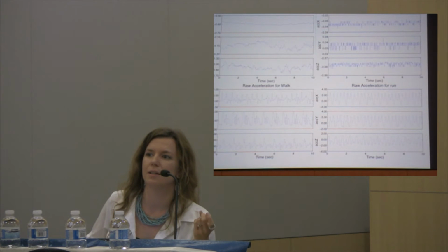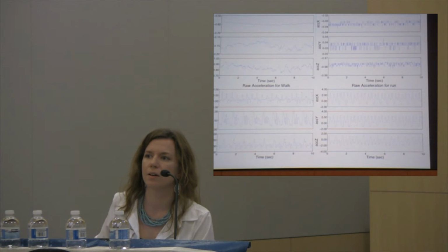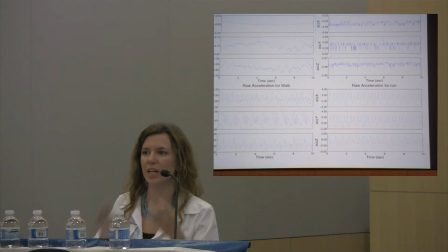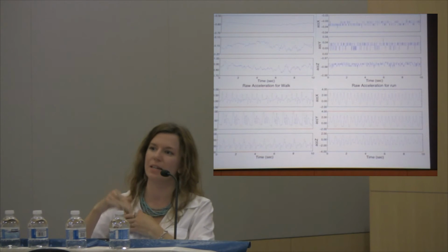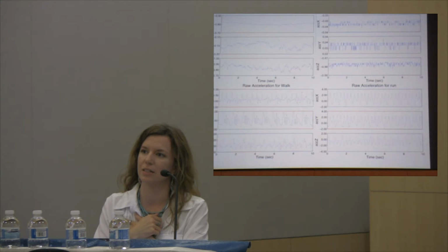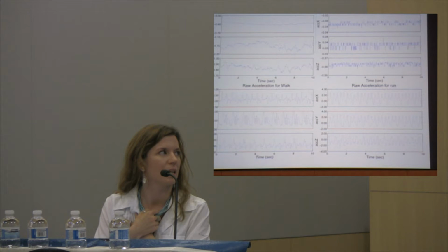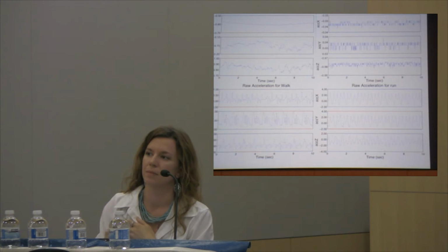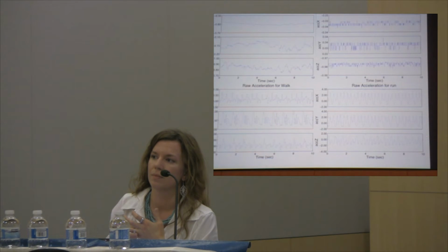Yes? What was the cause of the noise floor in the cell phones? Is it a mechanical noise, electrical noise, sensor? If you just isolated the accelerometer, could you get a better smartphone-based sensor? I don't know. We only tested the noise floor in the chassis of the phone itself. We haven't really explored that. You can turn off all the other functions and just use the smartphone as an earthquake sensor. The noise she's talking about is the actual sensor itself vibrating just slightly.